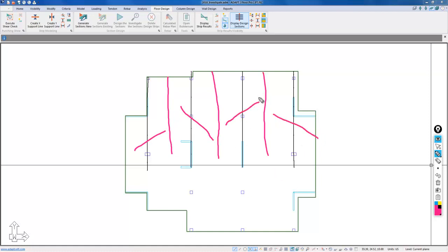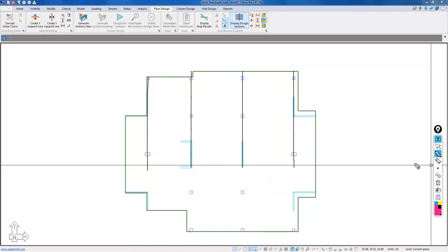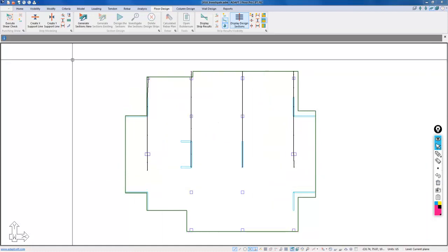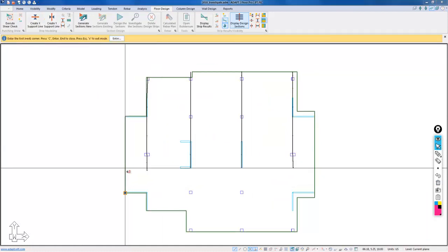But it doesn't know how far below to extend the tributary because the boundary that it sees below this point is really the slab, but the support lines kind of stop arbitrarily just inside of the slab. So to make sure we have a nice clean break for where the tributary regions are generated, we're going to create a splitter chaining these points together. And this splitter will be called a Y direction splitter. Again, it's just a boundary that we're imposing.